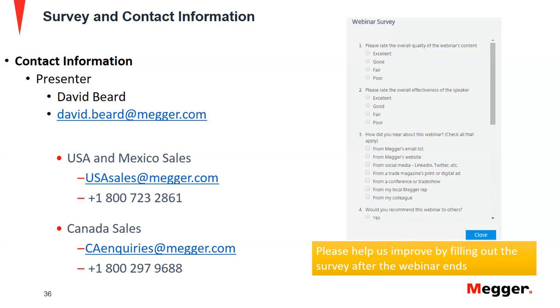if it's plugging into a panel using a test switch and going up. We do have a meter function inside RTMS as well. It allows us to put in a current, voltage, and some angle, on each individual phase, and then it will calculate whether the applied values compared to the measured values are correct or not. That gives us a quick wiring check. I hope that's what I'm answering, or if they're answering that correctly. If not, again, leave us some information. We have email, we have survey. That way we can better answer the question as well. But hopefully that gave you an overall idea.